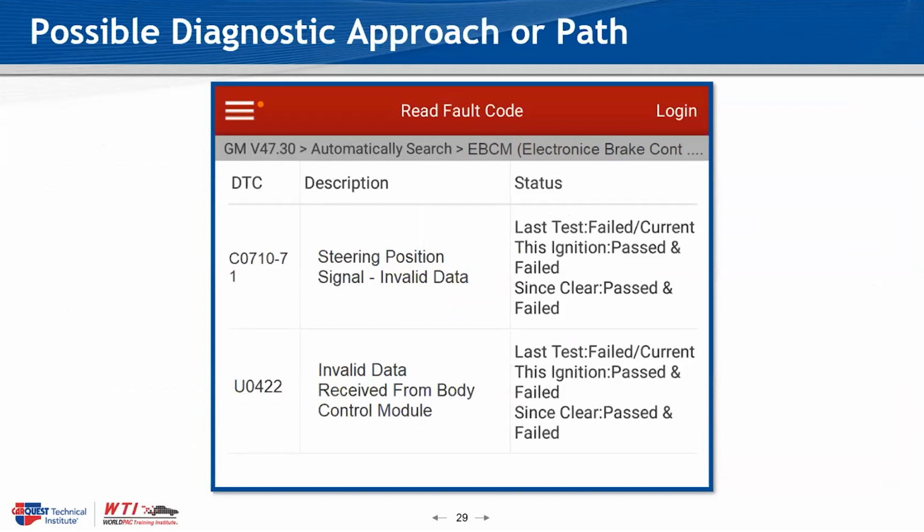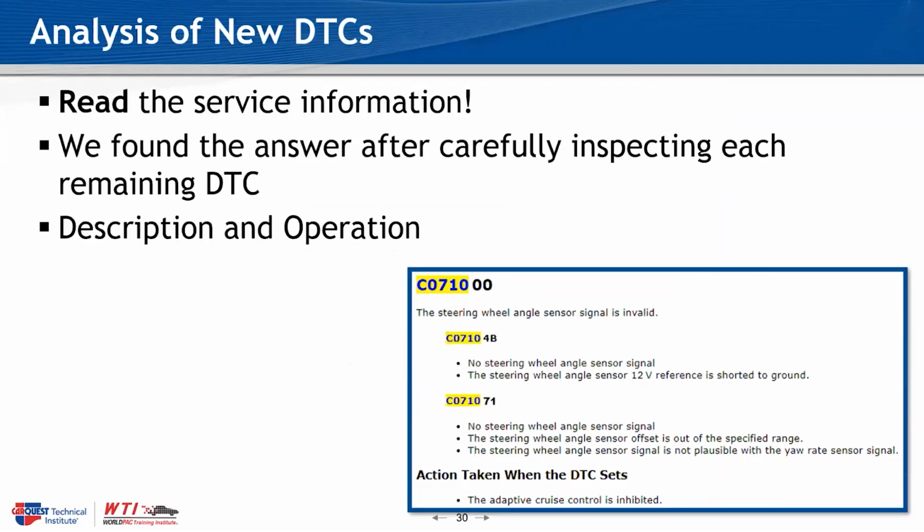Looking through all the information on every DTC, which is why it took hours, I found this one little excerpt for this 71000. And there at the bottom, the adaptive cruise control is inhibited. Apparently, when it's inhibited, it also sets this malfunction code if it does that during the calibration. If this code sets after a vehicle is calibrated correctly, I did not get to test that, and it was something brought up to me afterwards off the stream.